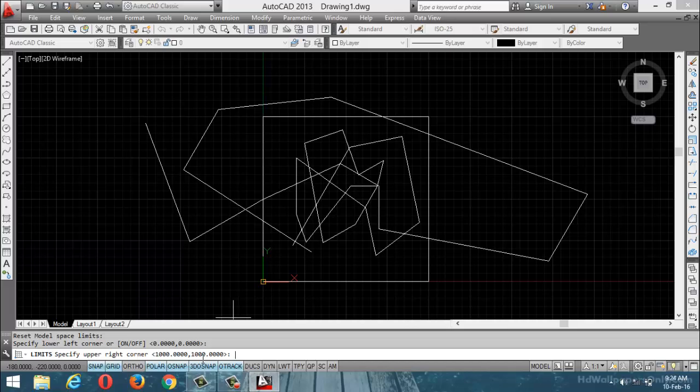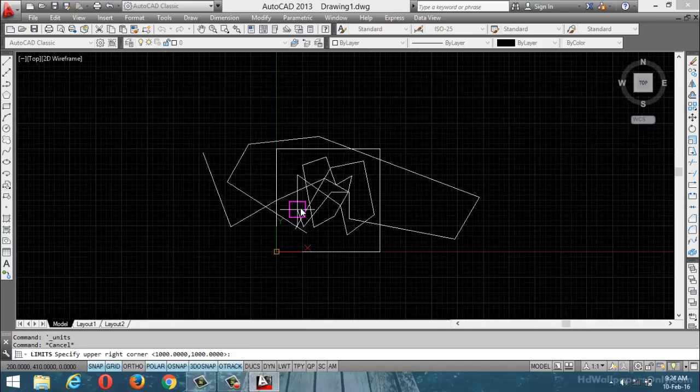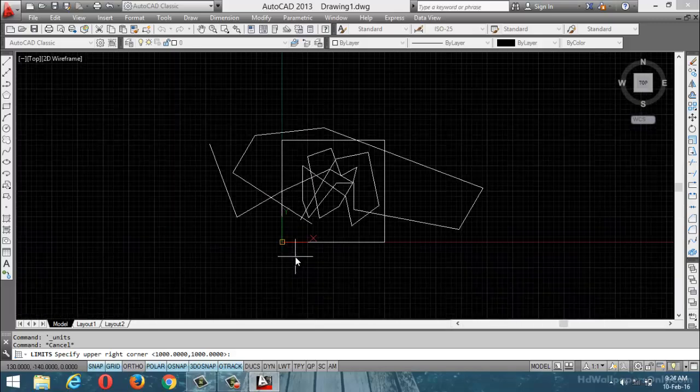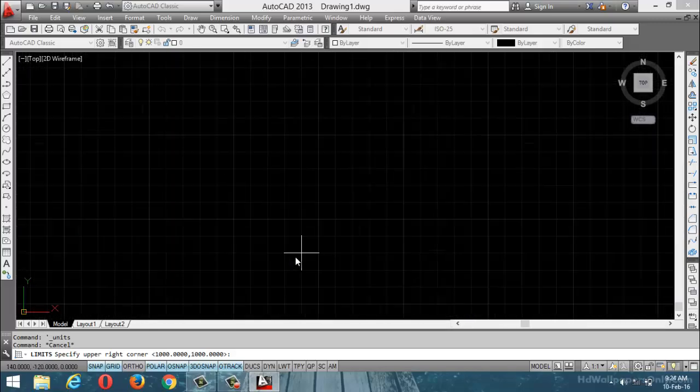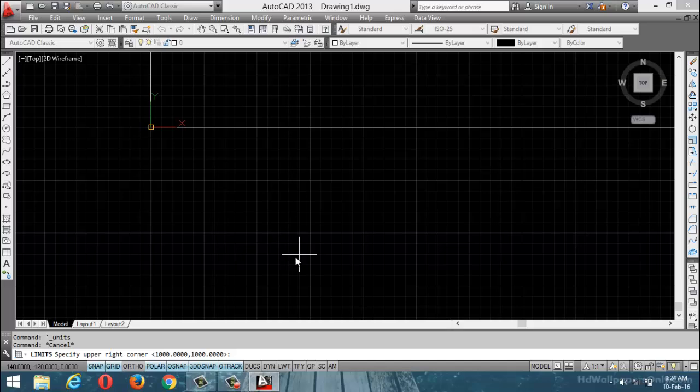Okay. Just write down the shortcuts. According to computer language, CMB1, CMB2, CMB3: computer mouse button 1, mouse button 2, mouse button 3. Nothing but left key, scroller, right key. You can use any one. Now just see it. Rotate the scroller. What happened? Zoom in and zoom out. Just write down: rotate the CMB2, in brackets scroller.